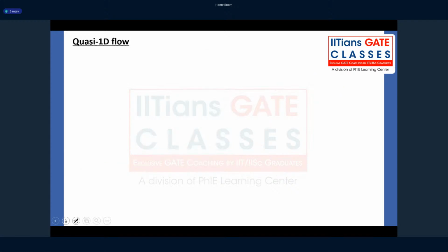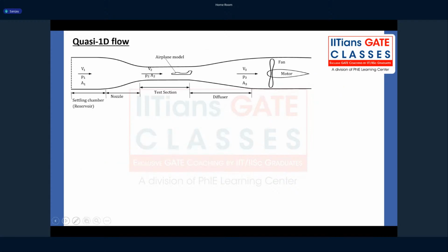Okay. So we will assume a quasi 1D flow. Quasi 1D flow means the flow properties only depend on one direction. If you take a variable area duct, the flow properties only depend on the x direction. They do not depend on the y direction, or they do not vary along the cross section, which means if the pressure over here is P1, at the entire cross section the pressure is only P1. The pressure is not changing across the cross section.